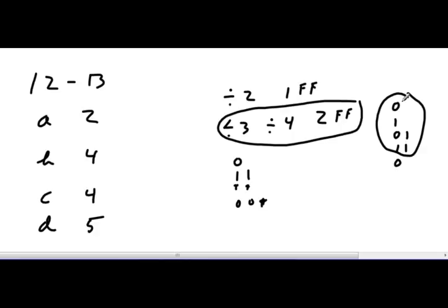So I have a state 0, I have a state 1, I have a state 2, I have a state 3, then I go back to state 0. So if I have an incoming signal and I divide by this and I wait for the 0 to happen, the 1 to happen, the 2 to happen, the 3 to happen, and then I change it, and then I wait for the 0, 1, 2, 3, and I change it, then that's a divide by 4.